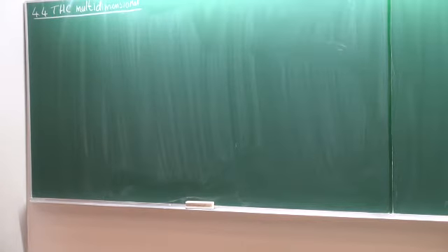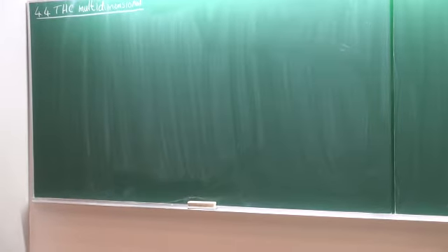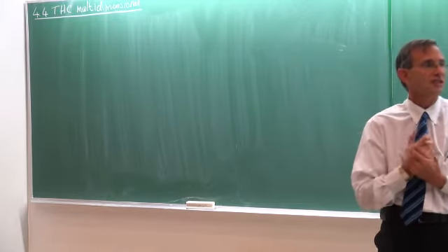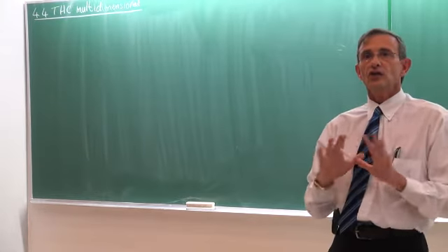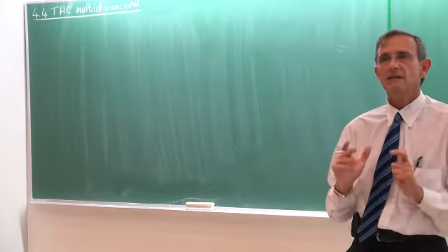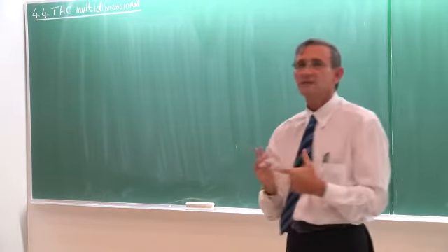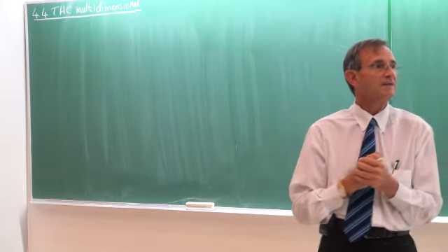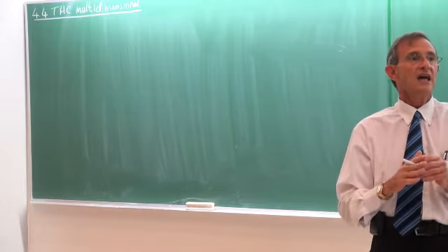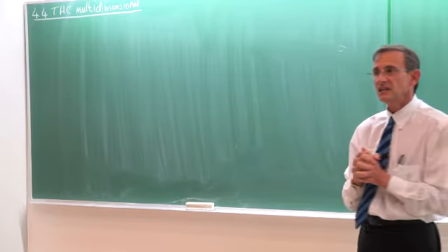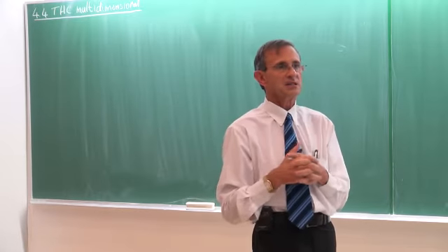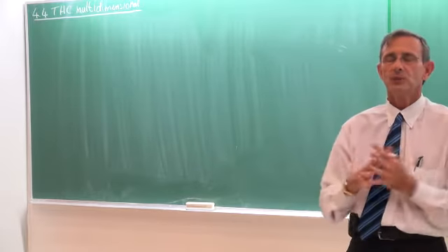Okay, ladies and gentlemen, let's continue with chapter 4 in the textbook of Cengel and Ghajar. Chapter 4 is on transient heat conduction. There are different parts. The first part is the lump system approach. Very, very simple answer, but very limited because it cannot give us different temperatures inside a body. All the temperatures would be the same, and the important assumption is that the internal resistance is negligible in comparison with the external resistance. About 10 times is the ratio.